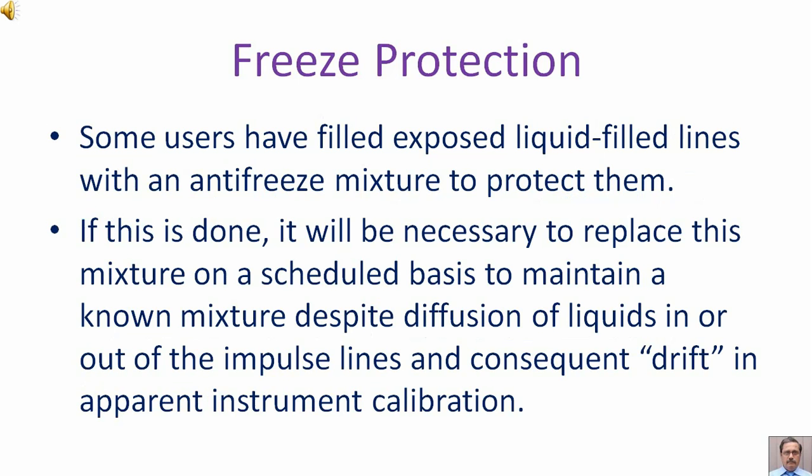Some users have filled exposed liquid filled lines with an antifreeze mixture to protect them. If this is done, it will be necessary to replace this mixture on a scheduled basis to maintain a known mixture despite diffusion of liquids in or out of the impulse lines and consequent drift in apparent instrument calibration.